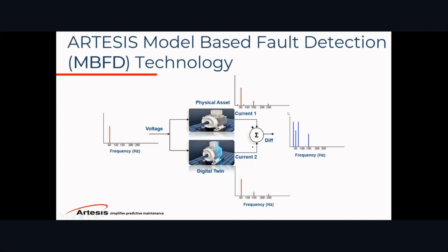So, we are analyzing this in the power spectral density, and we amplify them. We're looking at the frequencies and the amplitudes, and these will tell us what type of fault this is, and also how severe these faults are.